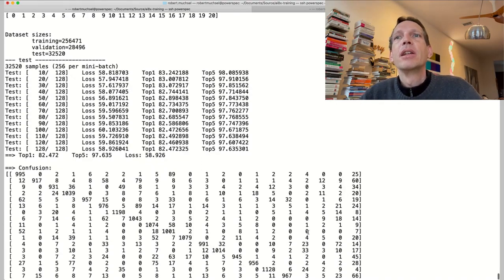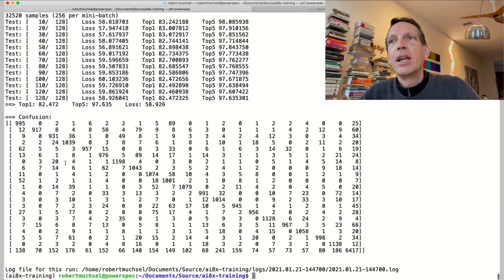So now you notice the top one with this file is 82.4, which is less than what we had using floating point in training. But this really tells you what the performance is and how much you lost during quantization. It's especially important when you're using 4-bit or 2-bit weights because the loss can be bigger. So before loading this file onto hardware, you definitely want to make sure that the performance is still acceptable. And this is what the evaluation step is for.